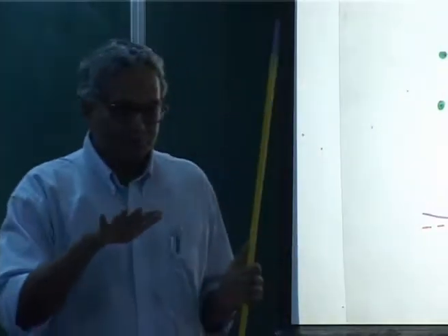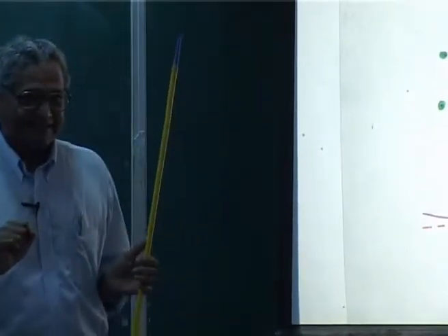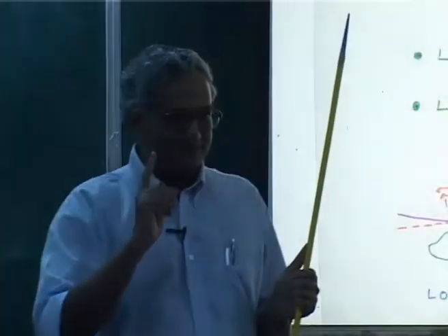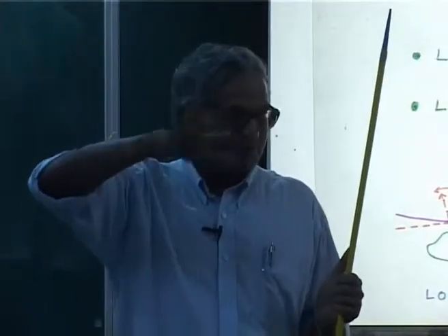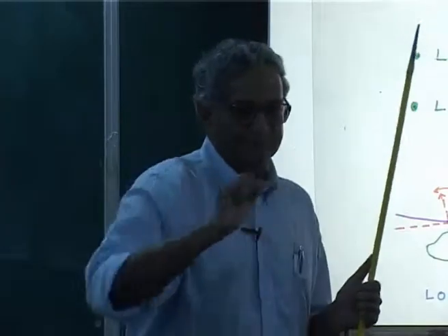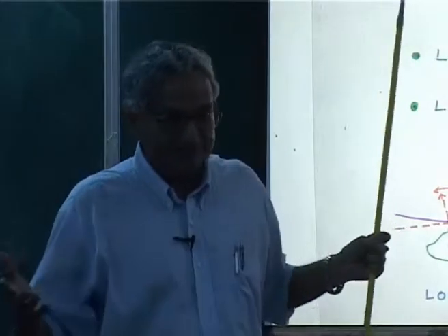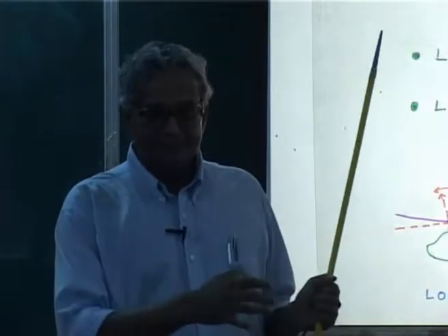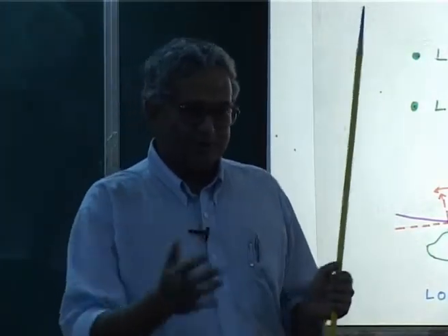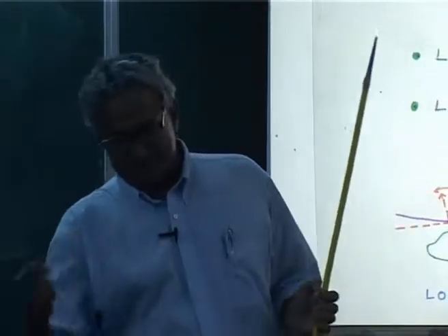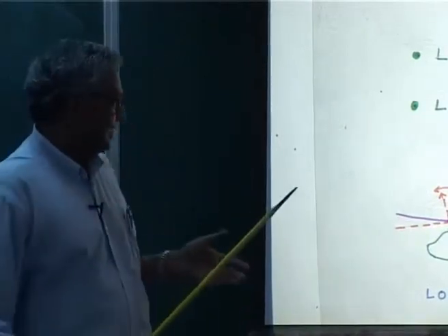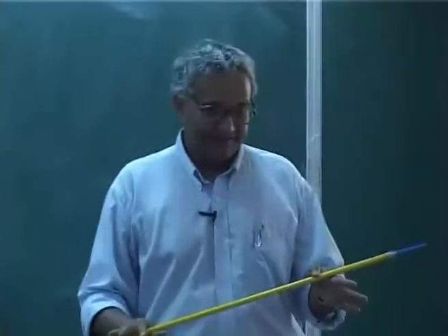Similarly, when you want to do longitudinal, because of the Coriolis, centrifugal, all those effects, the gyroscopic effect of the rotor, he will get a roll, which is undesirable, but you can't help it. That means he has to keep on adjusting. If he wants one, he will get an undesirable response, and he has to compensate for that. Okay. That is why helicopter flying is more difficult.